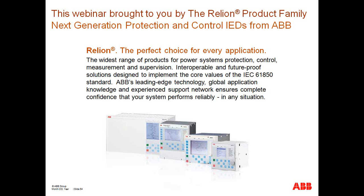So in the case of, let's say, a breaker fail scheme where one device is being tested and you're applying current to it, and that in turn is generating a GOOSE message that's used by another device to start the breaker fail timer. If you set that relay on test mode, the device that has the breaker fail timer will recognize that that device is in test mode, thus it will disregard that particular message, avoiding the actual operation of the breaker fail scheme during a testing scenario. So there are mechanisms that were thought of to ensure the flexibility of both operation as well as testing.